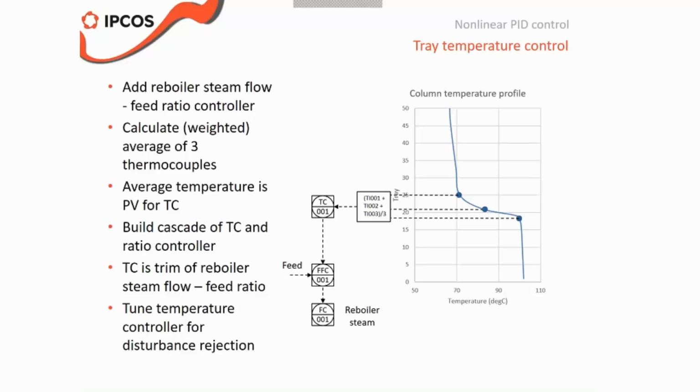Well, that's always a problem. This would happen, for example, if the flow to the unit changes. That means that the flows will change, and you will get all these kinds of non-linearities. I would still recommend using a characterization block in this case because it will definitely help. I mean, it's not easy to compensate for flow changes, and that's not an easy thing.